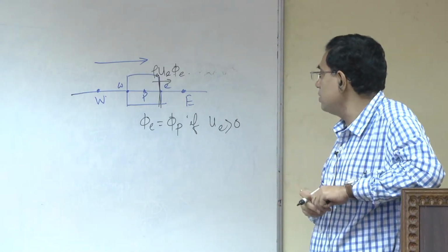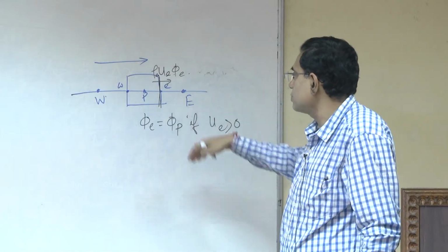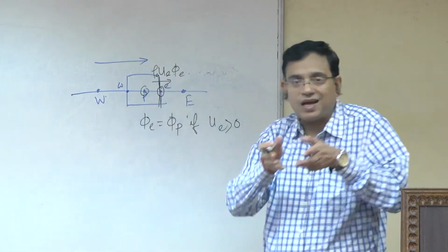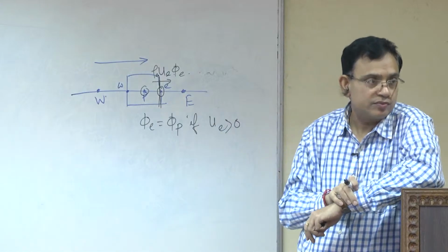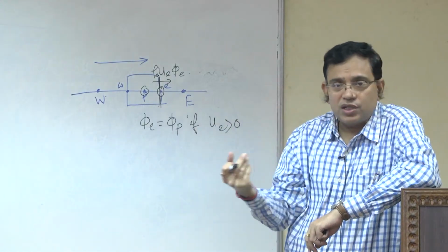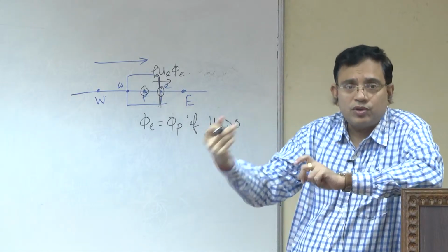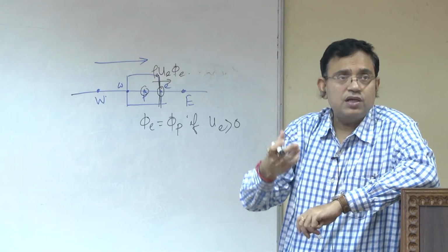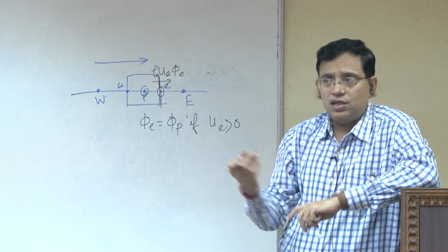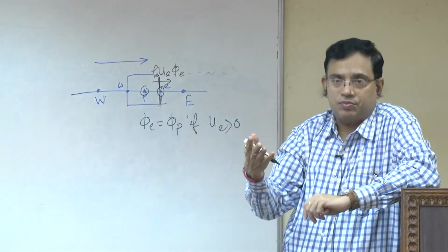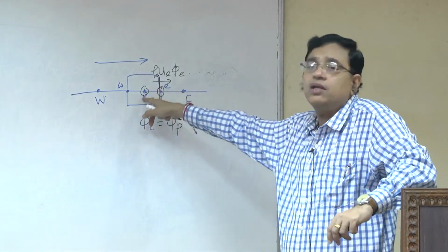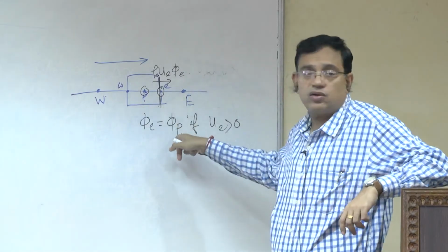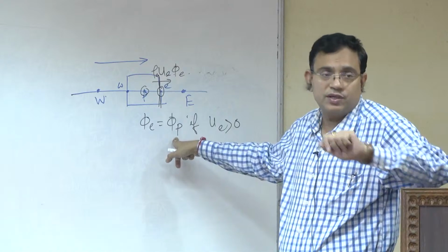So, what it is simply saying is that if the fluid is flowing very fast along this direction, then whatever the value of phi here is, it is mostly due to this. That means the upstream motion is influencing it the most, and it is quite logical, because the downstream will try to influence more and more when you have diffusion also in the opposite direction influencing. But if the Peclet number is significantly large, then the diffusion from the other side is not going to influence that much. So, the value of this is strongly influenced by the value of this, and that is the expectation of this scheme. So, instead of linear, it is just like a constant, even the simplest form of linear.